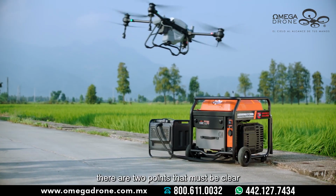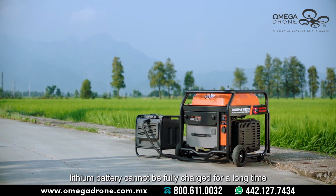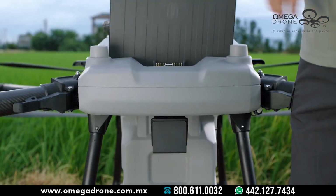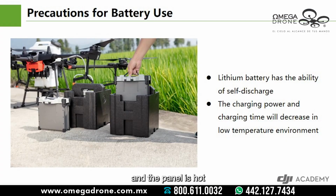There are 2 points that must be clear about the lithium battery. Firstly, a lithium battery cannot be fully charged for a long time. So the smart battery is designed with a self-discharge function. When you find that the battery has been fully charged for a period of time and the panel is hot, do not worry. This is due to the self-discharge of the battery to protect itself.